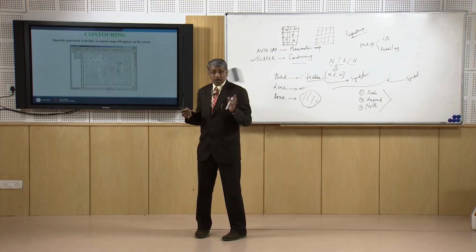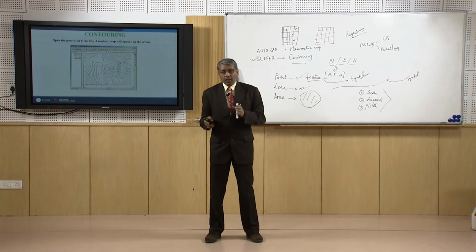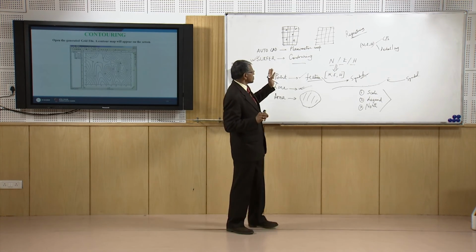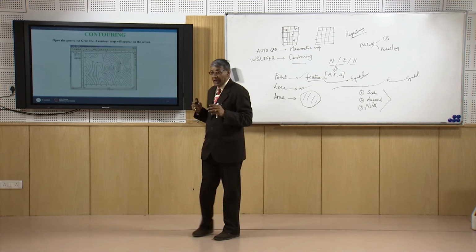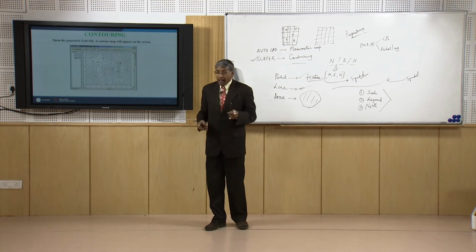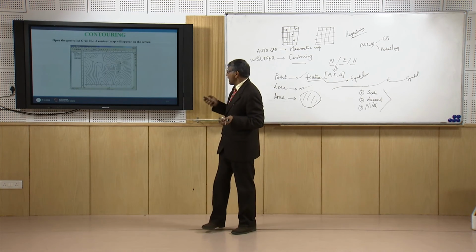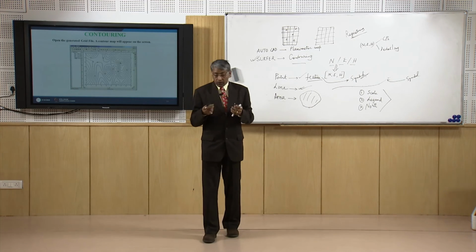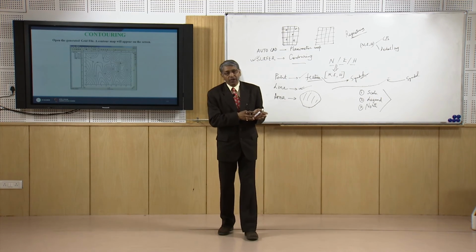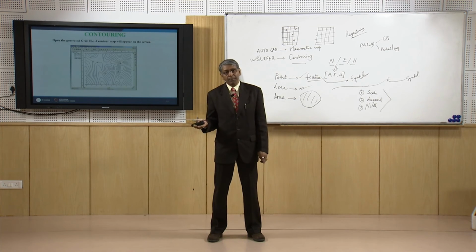So all those cartographic work has to be completed, and each one of the symbols should be noted down having the proper color. Contours should be noted with proper color, and every fifth contour should be a bit thicker, and contours should be identified along with the contour value. In that way we can complete our work, and the draft one we should compare with the actual field whether all the objects which we really want to have represented in the map are available or not.